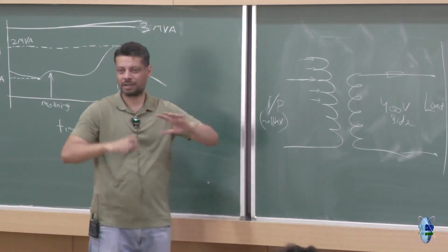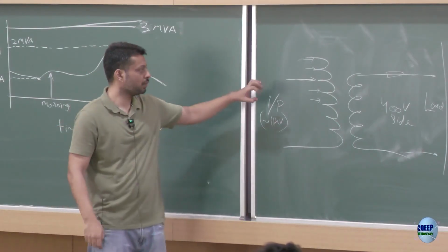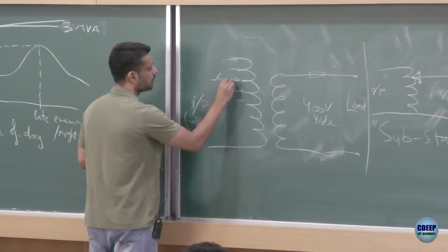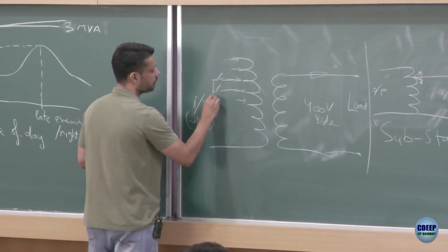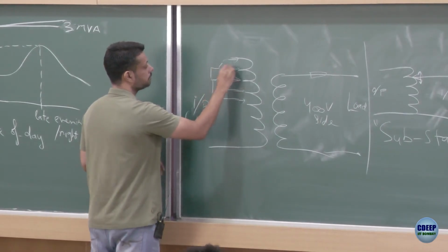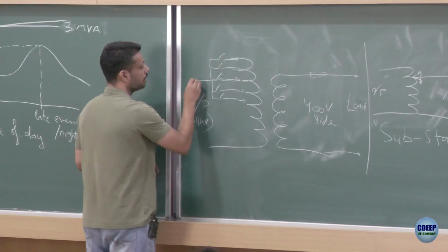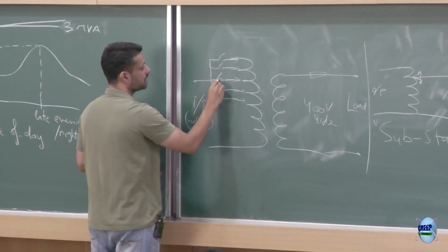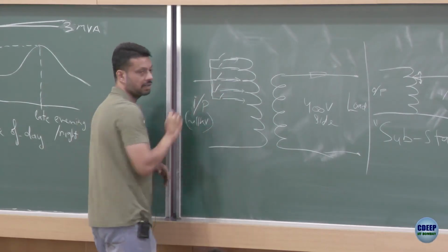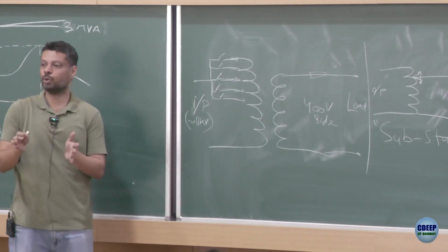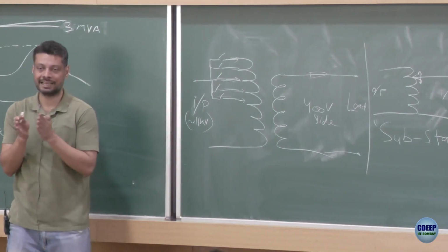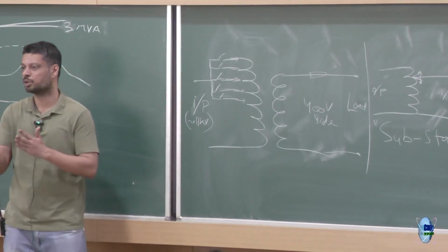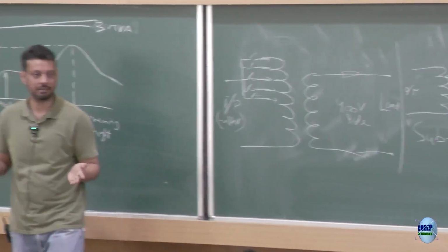So, you do not require very fine control anyway. Instead of that kind of mechanism, here you connect multiple switches, and then you can connect to this one, this one, this one, this one. So, it is doing something similar, of course in a limited range. You do not want to vary the voltage from 0 to 400 volt, you just want to do a fine adjustment of plus minus 10% or so.